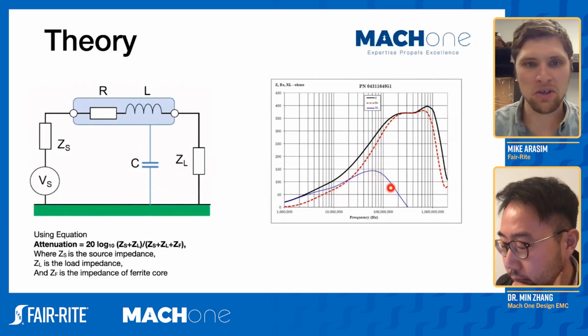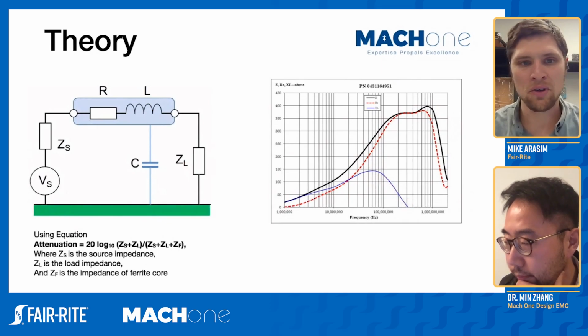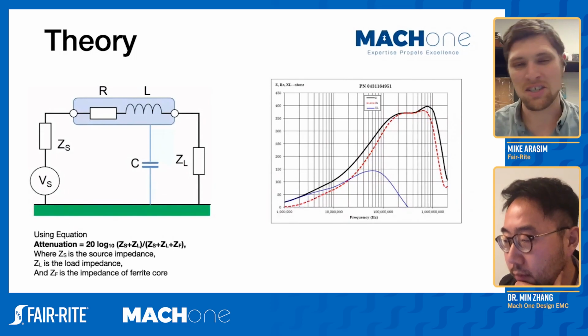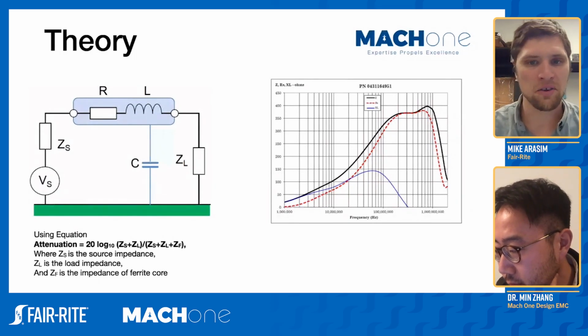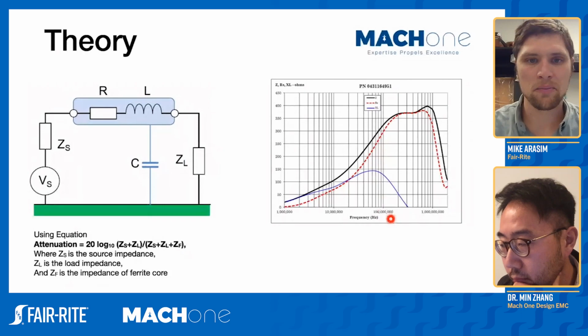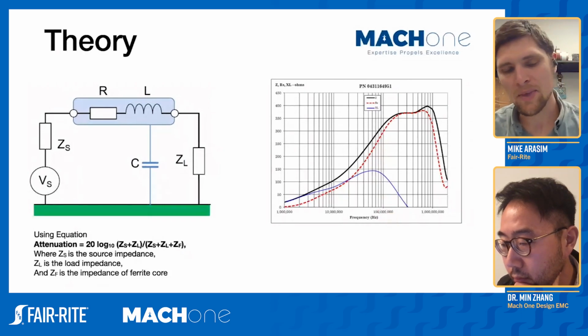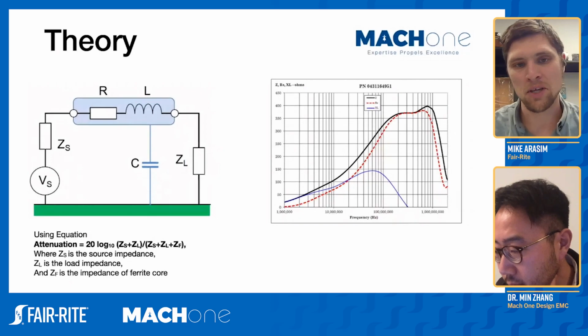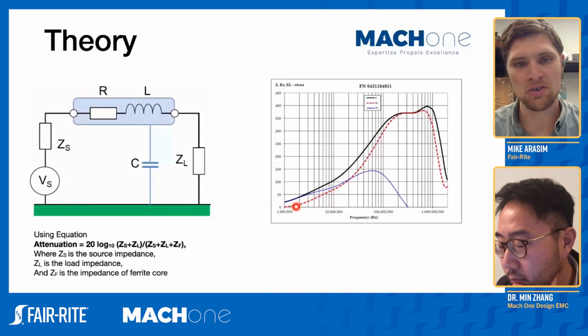Now, typically when we're talking about something like a 31 material, we'll rate it between about 1 to 300 megahertz. As you can see, it actually works higher than that, and if the chart were extended lower, you still would have impedance lower. But the important part is that 1 to 300 megahertz. At 1 megahertz, there may actually be better materials in terms of absolute impedance, but typically there's a trade-off in how broadband the material is, so you're not going to be covering those higher frequencies.